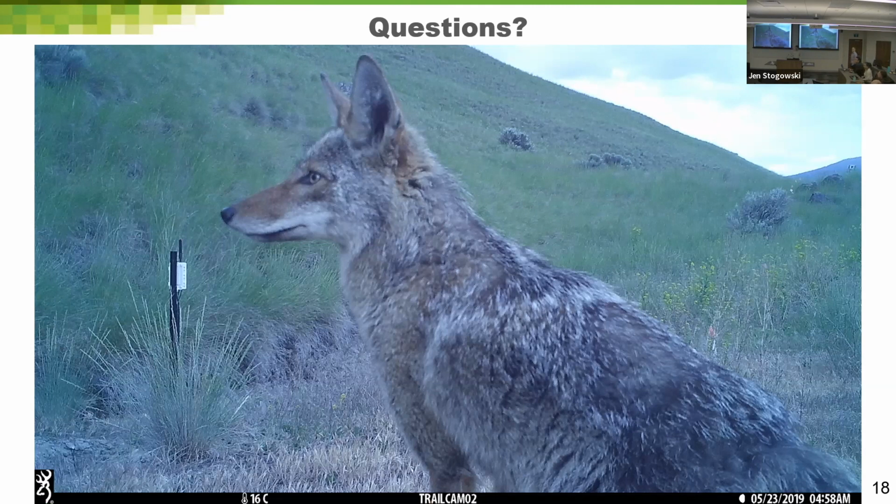Sorry, I see the trigger, the destabilizing process of saturation of the unsaturated soils during the spring melt or whatever. So that kind of points me towards possible mitigation, such as horizontal drains from the river level. Are you finished your research now? Yeah, I finished, defended in December. That is extremely helpful for understanding how these slides are activated, what the processes are, and how we can possibly target the causes.